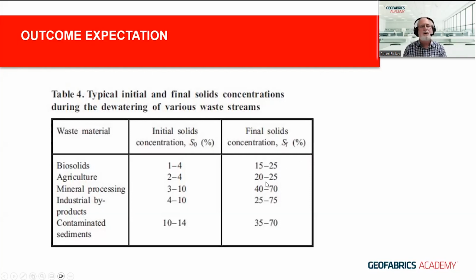Sometimes they can go a bit higher, but even at that stage, because the biosolids hold on to the water a lot more strongly, at 25%, that sludge will be spadable and truckable without a whole lot of water coming out. So you've reduced its volume significantly for trucking to waste.